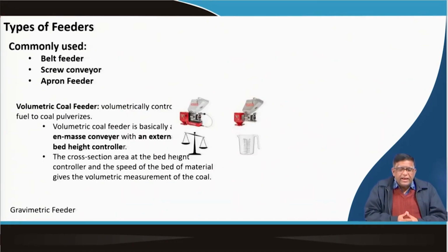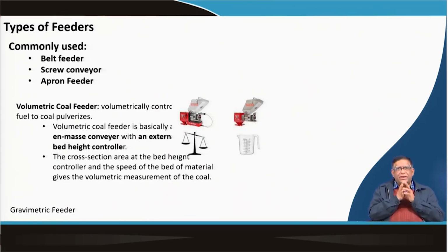Then there is a wide range of feeders, but the basic types are whether you are giving material by volume or as a measured weight, that is how much. Now, why does it come? It is because our bulk material sometimes could be a huge quantity. When we are talking of the mining and mineral or agriculture sector, agriculture will be handling some 100 and 1000 tons or cubic meters of material. In mining, they will be saying 100, 200, 300 cubic meters, even million cubic meters of material they handle. But you see some bulk materials in the pharmaceutical, cosmetic, and different manufacturing industries, where in processing you need to give an exact quantity either by weight or by volume.